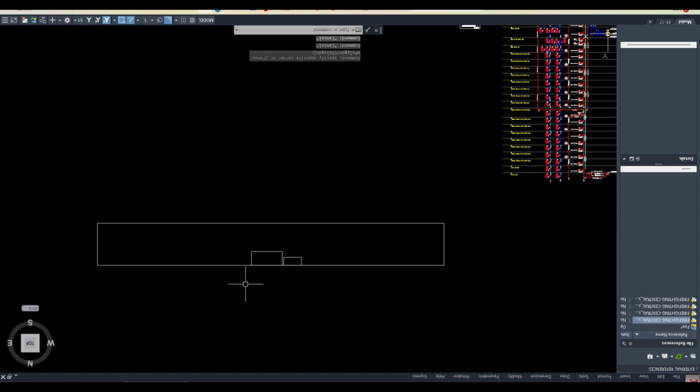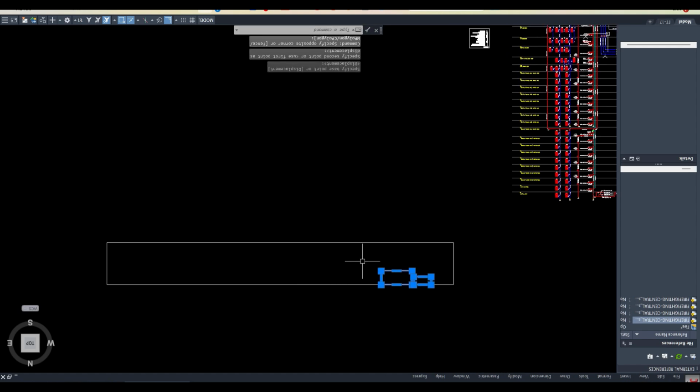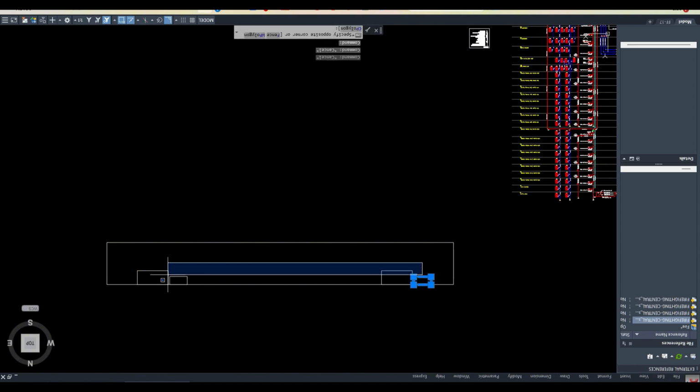Why is it wrong? Because in a building we need two fire exit stairs. Correct. And there is only one here. That is a part of the passive system. I told you, you remember, the passive system and active system. So that rule belongs to the passive system of the building design. You must have two staircases, two fire escape routes in the building. So for that purpose, obviously they will place them like this, right? And in that case you cannot have only one, so basically you have to arrange two fire hose cabinets in this building.